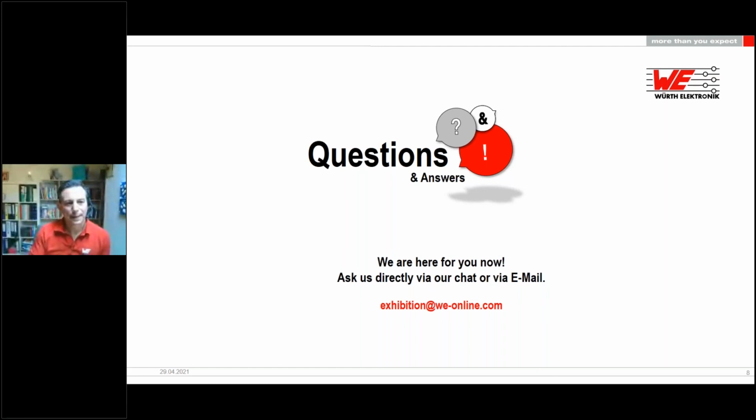Yes, I think so. Another one, what's the distance range between transmitter and receiver? The maximum distance in our system is 10 millimeters, as we have limited it so that with worse or less coupling we stop transmitting energy. This can be programmed by yourself as it's a development kit. For sure, you can increase the distance, maybe 15 or 20 millimeters, but then you have to accept lower efficiency and lower coupling. In general, this depends on your whole system, how big the coils are, how much distance you allow, and how much efficiency you would like to achieve.